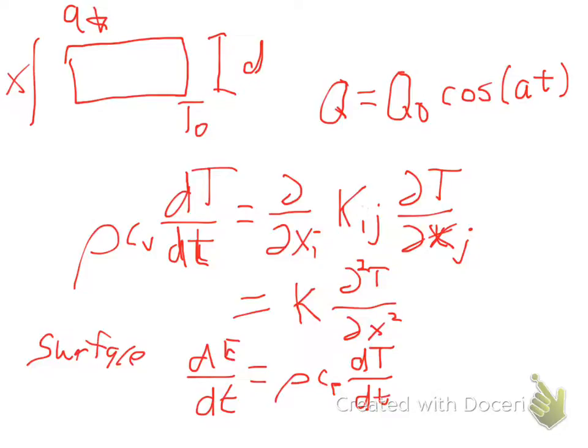You need to relate what the surface temperature is. Well, it would be what the flux is at that boundary. It's still a flux at that boundary. You're not going to convert it into a temperature because you don't know the temperature until you've solved the whole problem. So you will keep that as a flux boundary condition. You just need to write it in terms of a flux, which using Fourier's law is K dT/dx at that location.